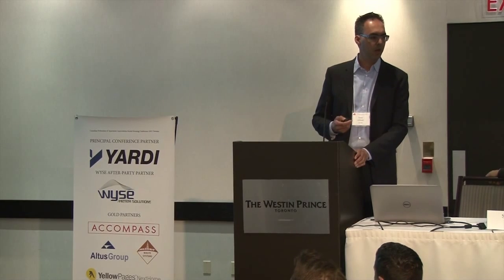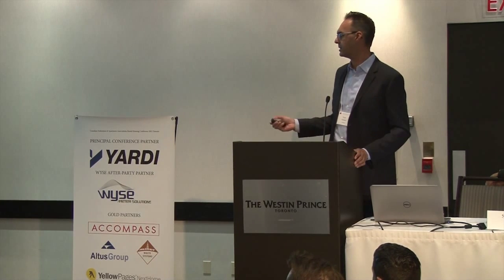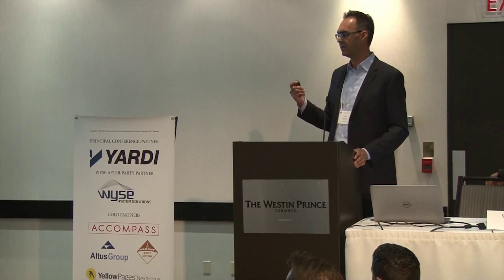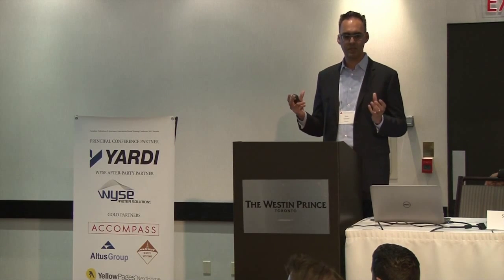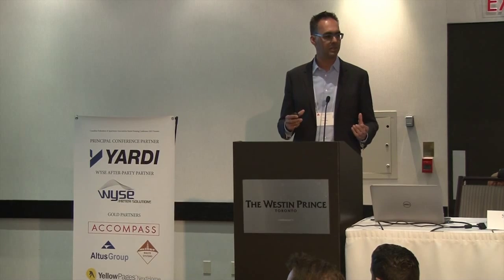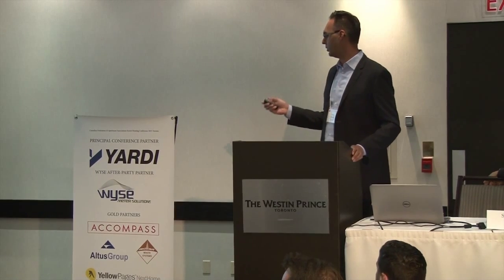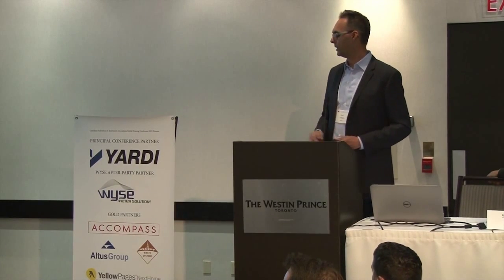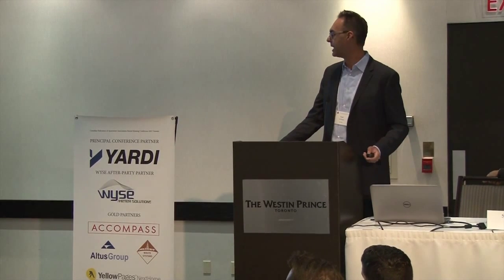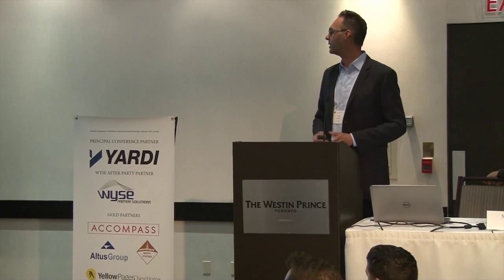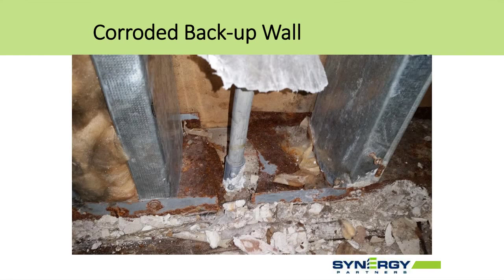But it's been ongoing for a long time, and this isn't just in one unit. This is something that's throughout. It's a systemic issue. It's throughout the building. There are some systemic issues with the window construction and age, and also with the sleeves for the PTAC units. And then within the wall assemblies as well, there's corrosion.